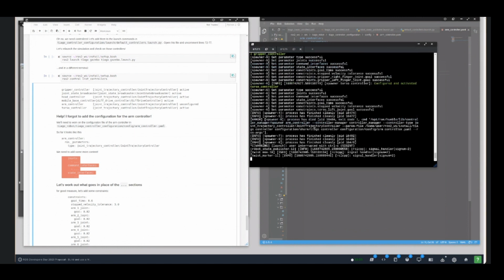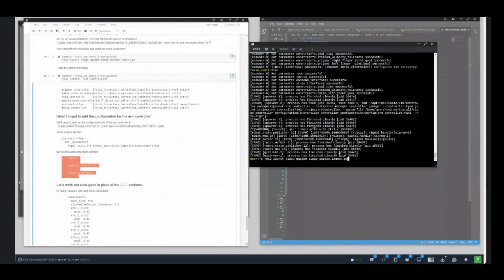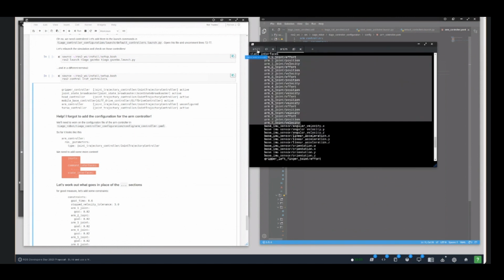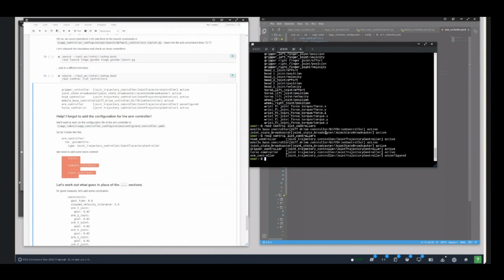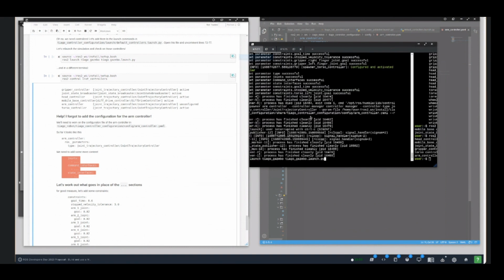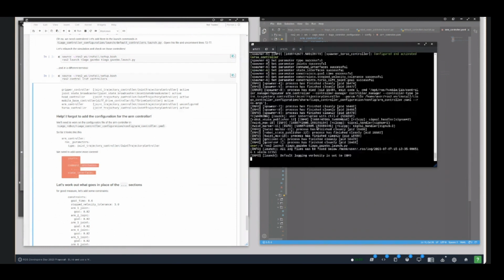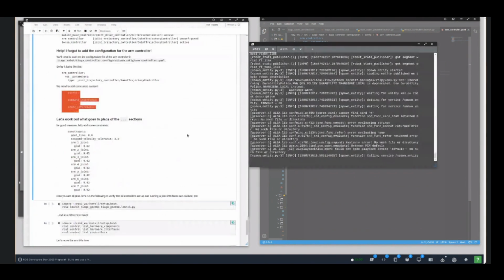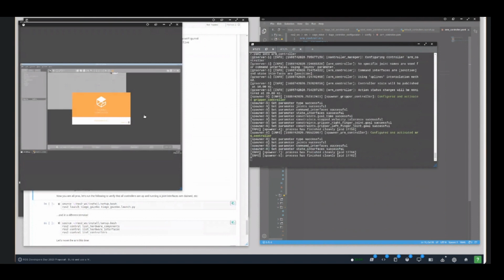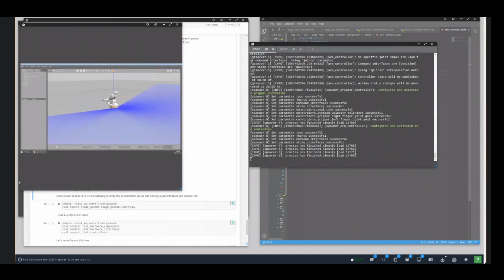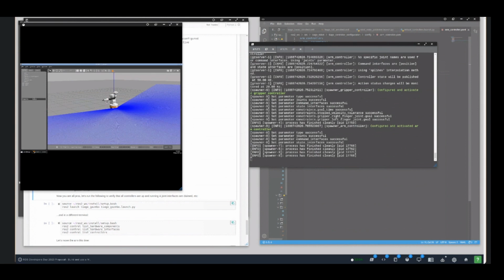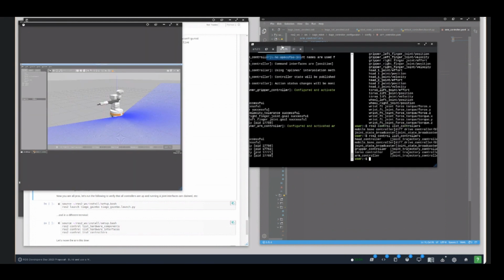I can, of course, also omit one of those joints, and that would just mean that the controller we're configuring is not going to be controlling that joint of the robot. The robot may look weird and have a numb joint in its arm. But whoop, as you can see now, we're definitely doing something to the robot, something different than before, because now the arm is not falling. Some stuff is moving there, which means that the force torque sensor is active, so forces are acting on it.